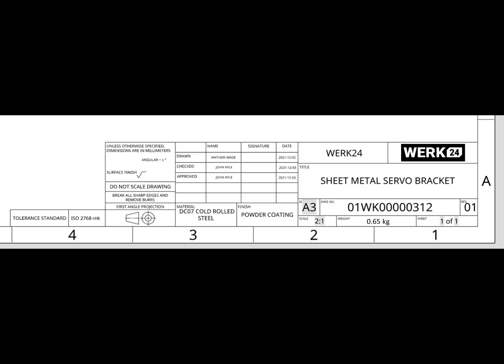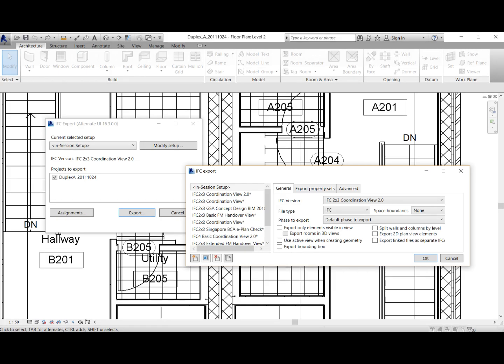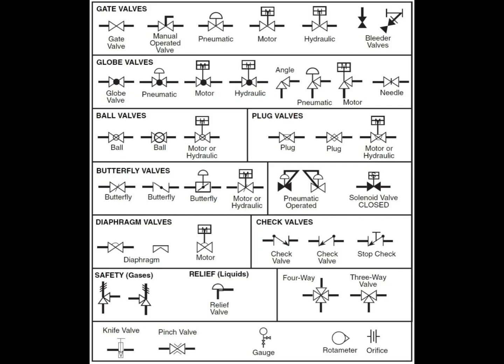Step 1. Control the drawings and lock the scope. Before measuring or counting anything, always start with drawing control. Confirm the drawing status. Check whether the drawings are issued for construction, issued for tender, or for information only. Record the drawing numbers, revision numbers, and issue dates. Clearly define what disciplines are included and what is excluded. This step prevents scope creep and avoids disputes later in the project.